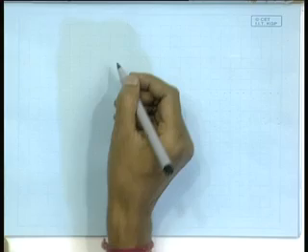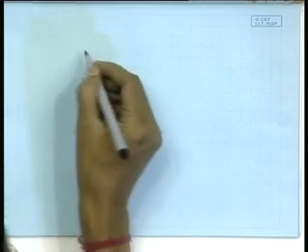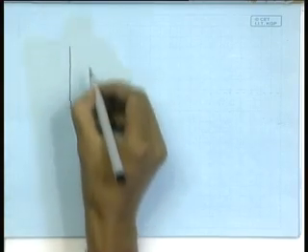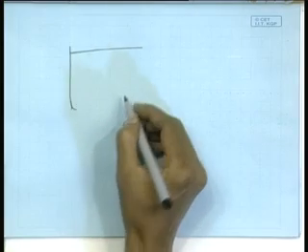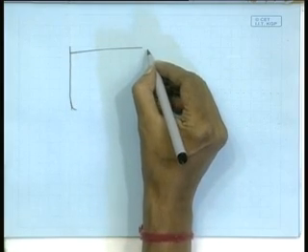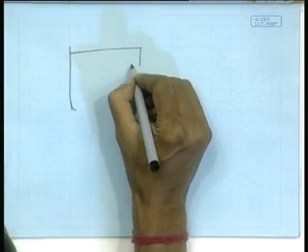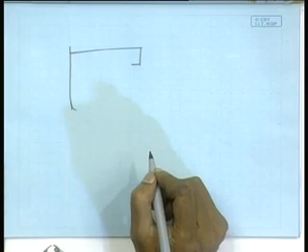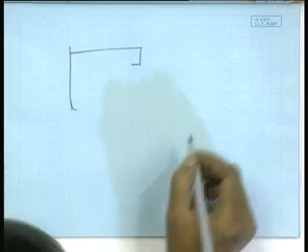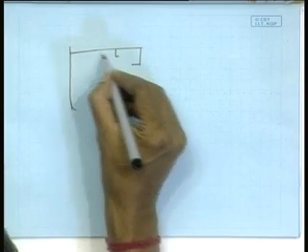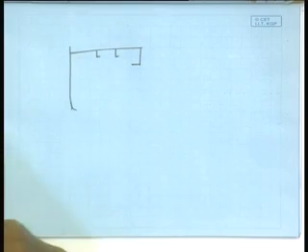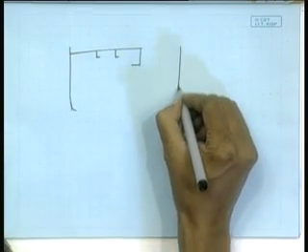We will just take a look how it is done in other vessels. Say general cargo ship. Once again, you have the deck opening. So, stiffening of this was done by means of a hatch side girder, right? And then stiffening of the deck, you had those deck longitudinals, etc. In case of a bulk carrier, what we did?